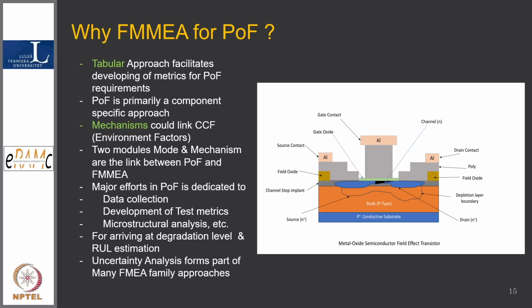Suppose my system is safety critical, so I'll find two, three components which are failing in unsafe mode, and I'll use this, which is what as a part of PRA we have done many times. Because if a card fails in safe manner, no issues, my plant will be shut down. Of course, that also should not happen, but safety comes before performance.